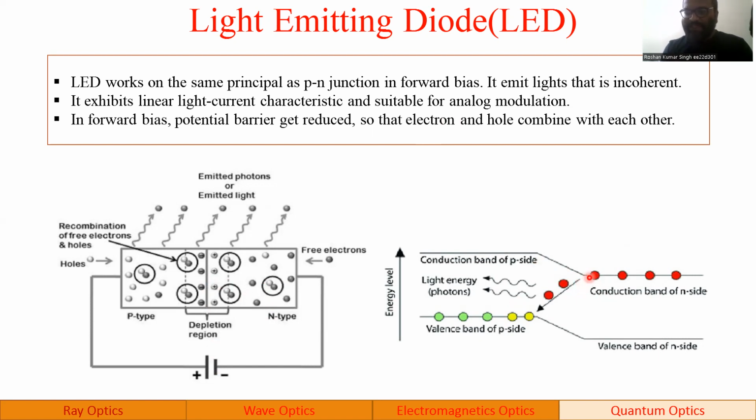For fabrication, it is necessary that the movement length across the PN depletion width must be greater than the recombination length of the electron, so that it can recombine. Otherwise, if it reaches the p or n side or crosses the depletion region, then light cannot be emitted.